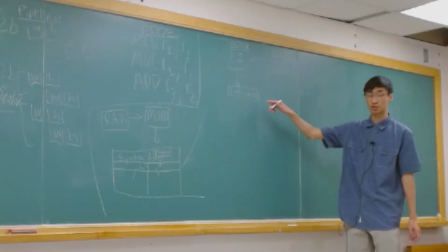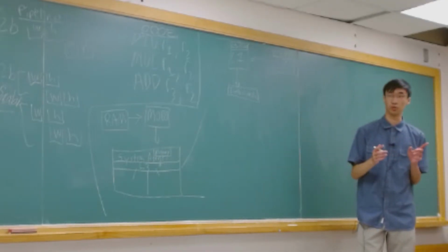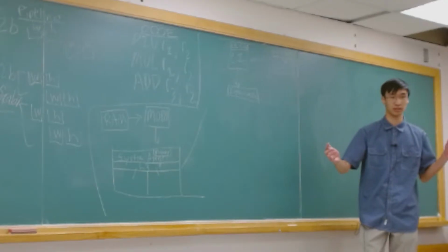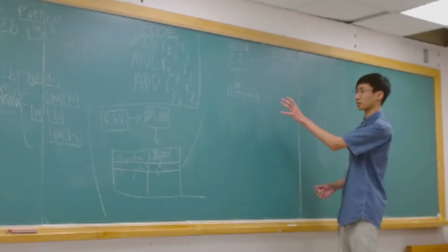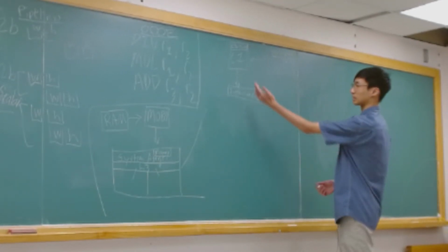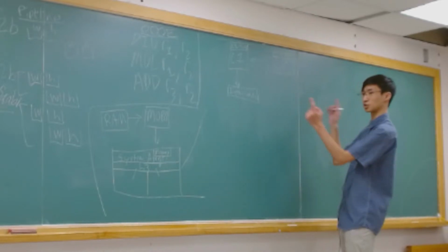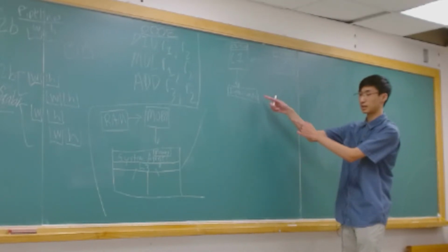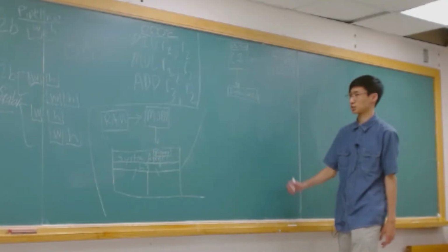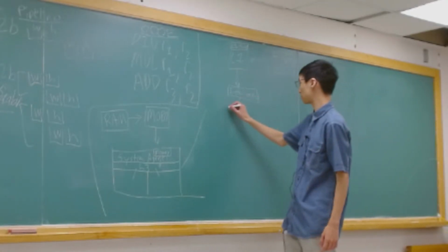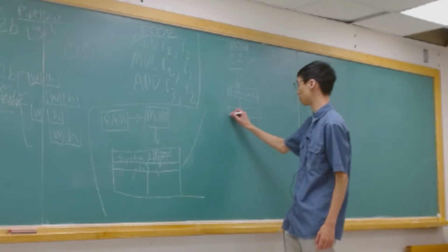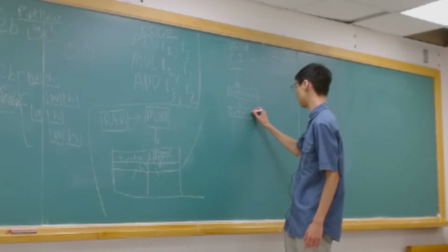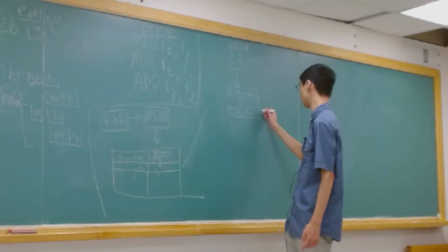And this instruction fetch's job is to do the variable length instructions stuff. As you know, instructions in x86 are variable length, and we need to be able to find where all those instructions are and begin decoding them. So that's that guy's job. We'll pull out 16 bytes-ish. The next part is we will push that into our instruction queue. Oh, I'm running out of space, eh?